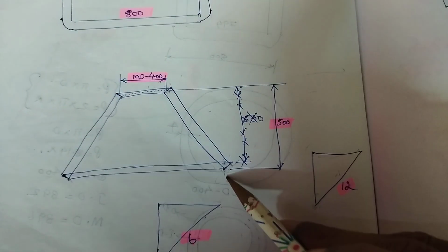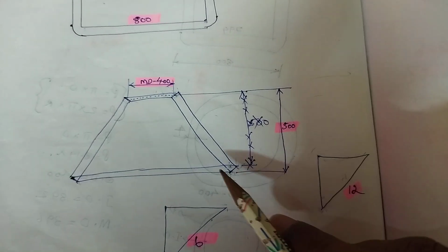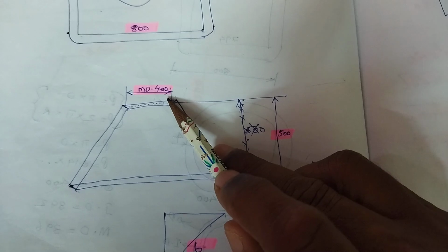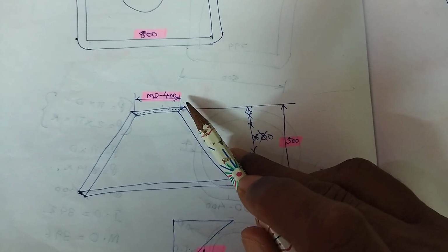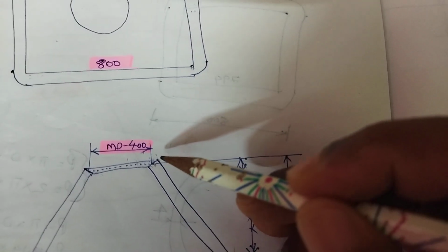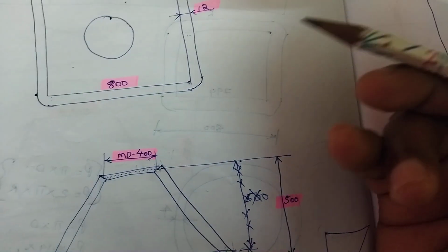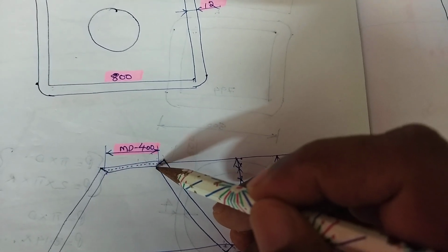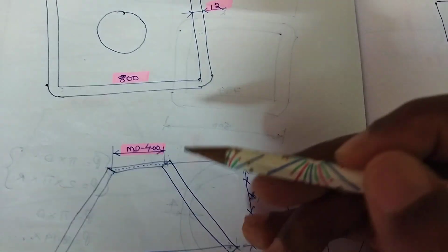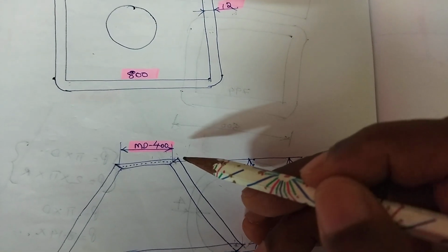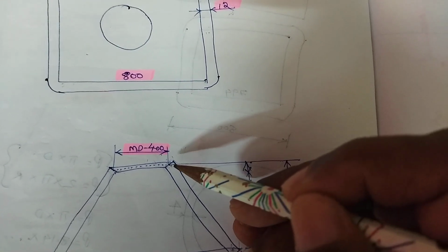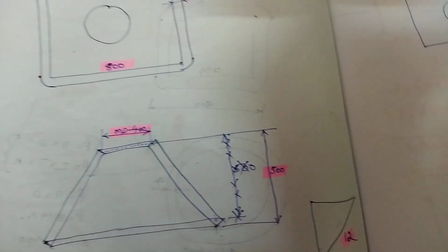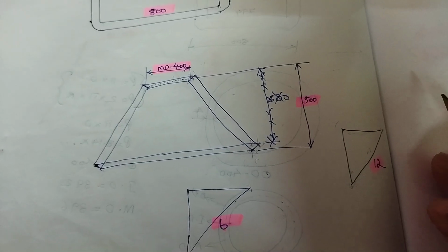If it is a square to round job, it has two portions. The square portion is on the bottom side and the round portion is on the top side. So for the top side, we shouldn't take its outer measurement which starts from this corner to this corner, and we shouldn't calculate its inner corner starting from here and here. We should take the measurement of the medium diameter. It starts from in between these two lines. Okay, that is the speciality of round portions.